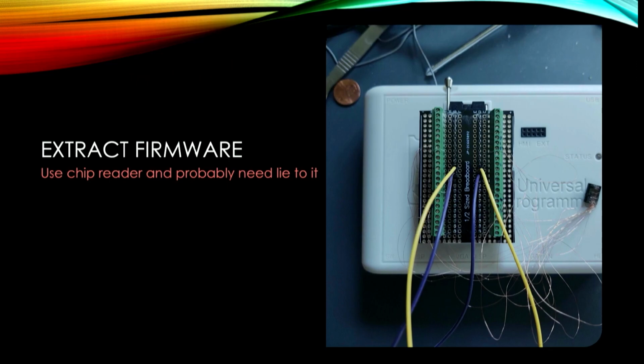In this particular case, when you read this in a flash reader, two things will happen. Either it'll recognize the chip ID, because the first thing it does is it checks for the chip ID. If the chip ID matches, it'll read it out to you. Turned out this one actually matched the chip ID, so my first pick was right the first time. And that's amazing considering these places produce hundreds of different types of flash memory chips.